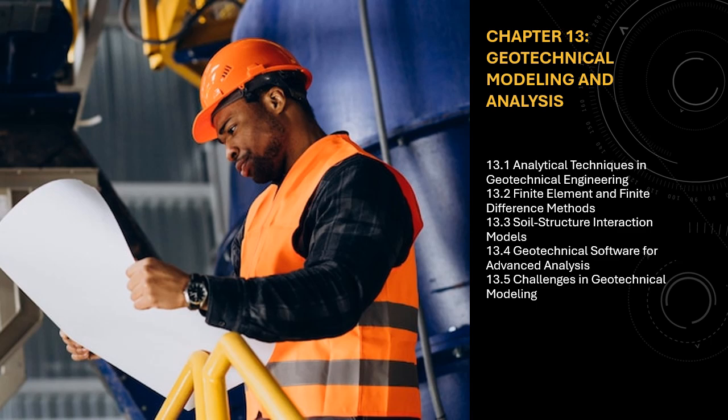Mitigation. Using a site-specific calibration process is essential for improving model accuracy. Engineers should also employ back analysis techniques, where model parameters are adjusted based on observed field performance to improve predictions. Incorporating real-time monitoring data into the model during construction or operation can further refine the model.